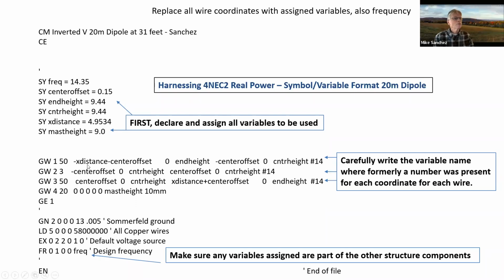It is an arbitrary number, but there's rules for using. So given a certain distance, there's a minimum segment distance you can use. So if you put in too many segments, you'll end up making a segment too small. When you have a very simple geometry, you do not need as many segments.